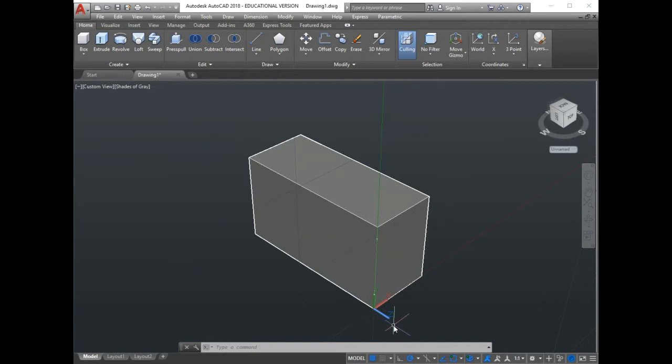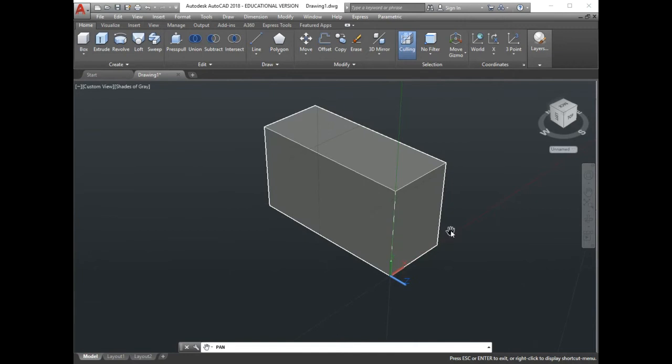No, the Z axis is in this direction. Just try to apply the right hand rule. Imagine that you are rotating your power screw from X to Y, so you are moving anti-clockwise. This means that your feeding will be outward. You go from X to Y, then the Z axis should be outward.